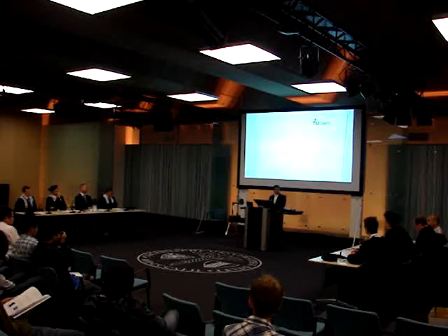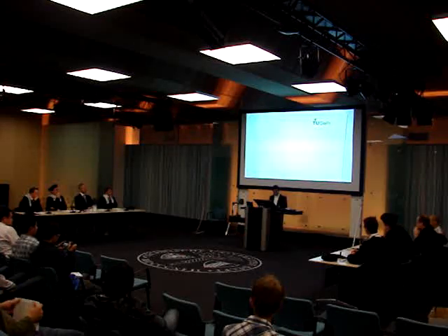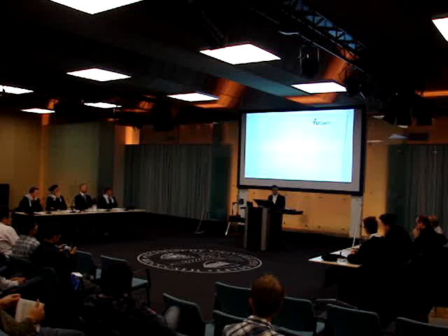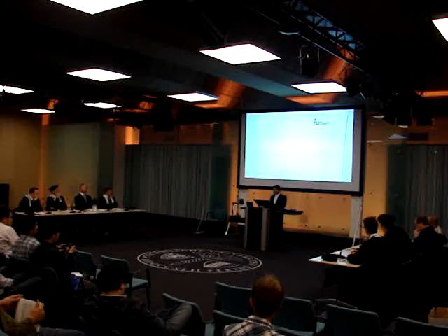So, at the macro scale, if you are in the elastic regime, I can use a small RVE. However, if you are in the hardening regime, I have to use a bigger one. And for the softening regime, I can use another one, because it serves different purposes. So that's why we need different definitions of RVE. That's my humble opinion. But my question is about the continuity of the definitions. I would like the two definitions to come together at the peak.